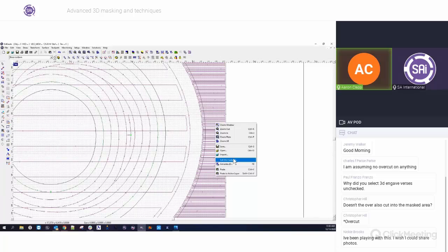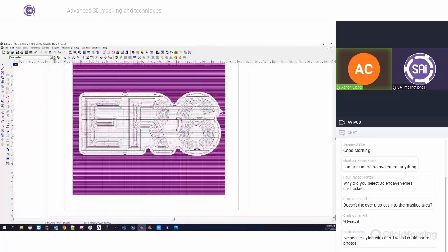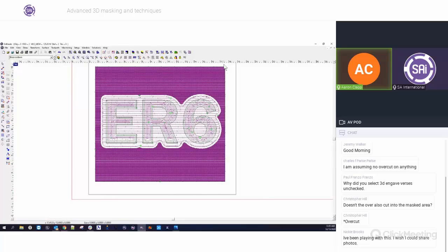Instead of doing that, I could simply make my 3D relief a little bit larger and then just have an end mill slice off the edge, so that I don't have to worry about whether it's going to be big enough or not. I can make the 3D relief slightly larger on all sides. Doesn't have to be much, maybe 1/4 of an inch, maybe 1/8 of an inch. Doesn't really have to be a whole lot.